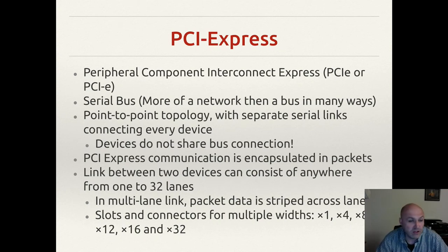Now, you do get additional benefits with serial, because when you remove skew as a problem, you can very often shrink the amount of time between the information moving and settling down, and get even more on that line. And then above and beyond that, you can introduce ideas like compression and some smart ways to move the information, which also helps as well.